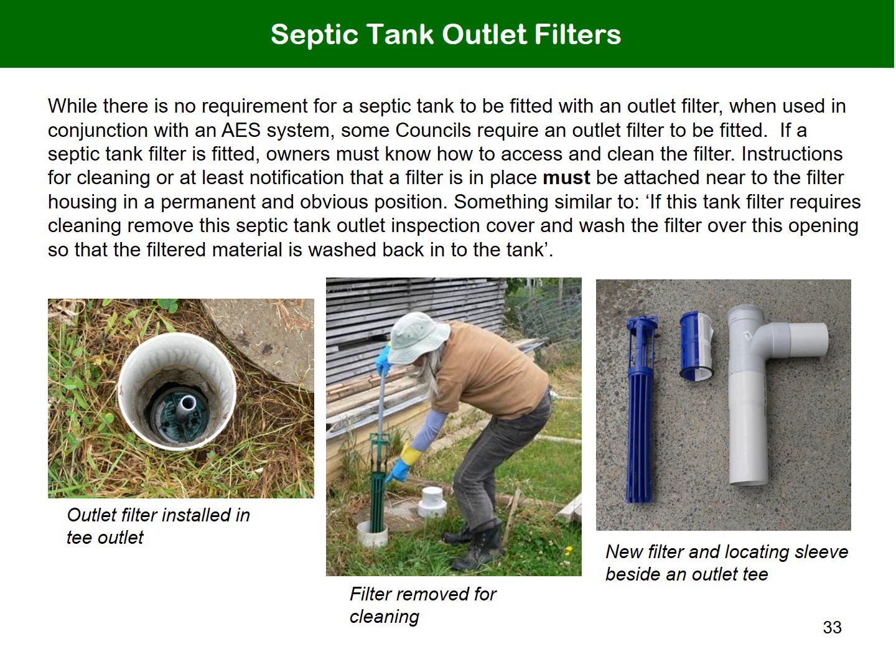Designers are required to provide an alternative air path around the septic tank if the terminal vent at the building must be used as the high-level air outlet vent. This is to avoid the risk of a blocked filter also blocking the airflow through the tank. Tank lids are required to be sealed in this case to provide a sealed air passage for venting purposes.